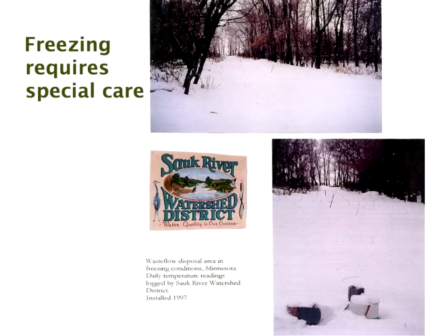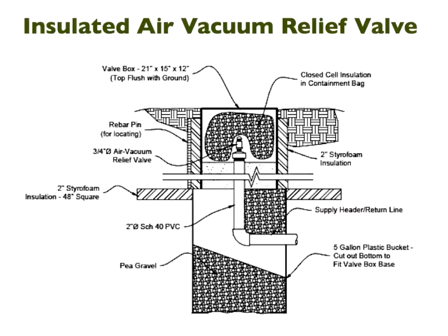Thank you. Okay, and freezing works, there's no question about it. There's a large number of systems working in freezing conditions. This is one that was installed in 1997 and was monitored. Incidentally, the more snow, as I think is fairly obvious, the better. When you do have problems with freezing, it's when there's no snow and you're not getting the insulation from the snow. But one of the most dangerous areas is the air vacuum relief valves.